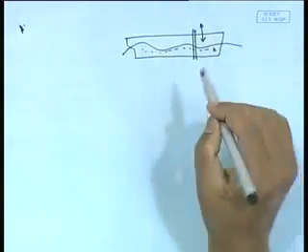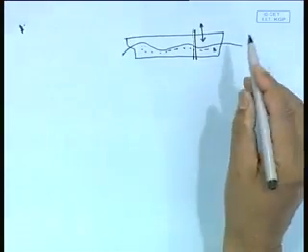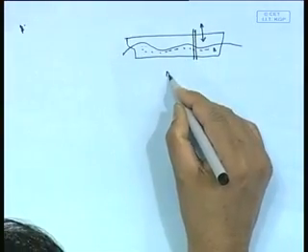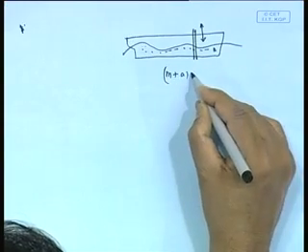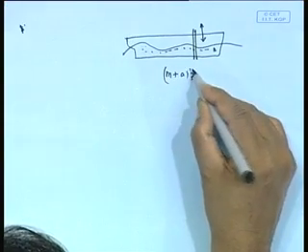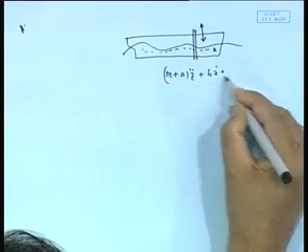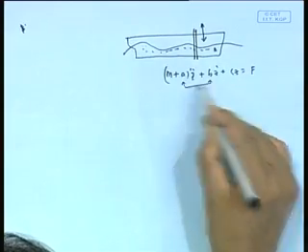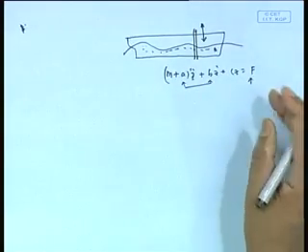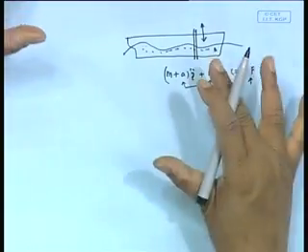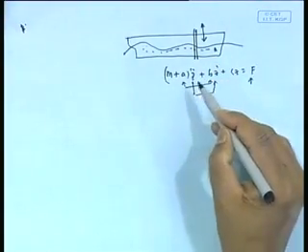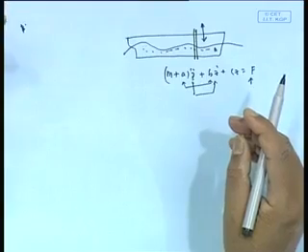What we have done in the equation of motion is we have mass plus added mass into acceleration plus damping plus this thing equal to force. See, this was a force, this was a force. All these forces are already calculated inside. On top of that, we calculate the motions, which also may give an inertial load.